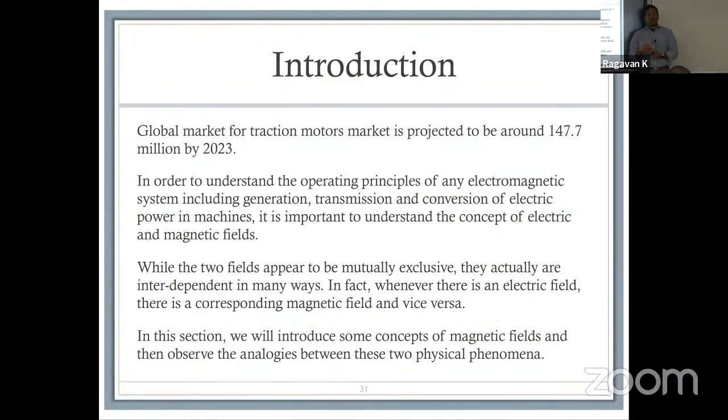If I reduce acoustic noise, what am I doing to the thermal behavior? Am I reducing that as well? Because the modes of transfer of your noise to the ambient are very similar to the modes of transfer of heat. So when you're designing a machine, if you're trying to extract heat from the coil winding, you're sending the heat over to the surface. You have fins and whatnot, but it is basically a contact-based system, right?